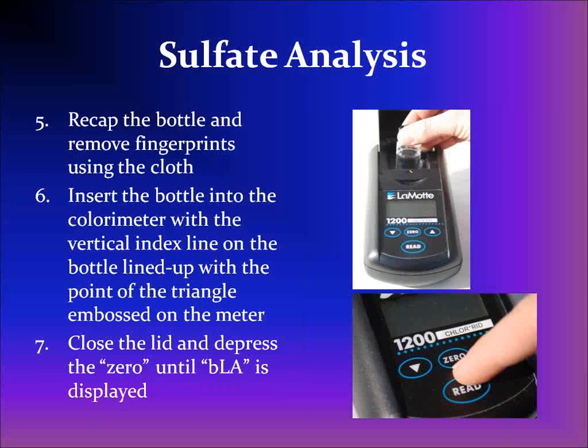After the extract is filtered, replace the cap on the glass vial and remove any fingerprints from the exterior of the vial using the cotton cloth provided with the kit. Any remaining fingerprints can affect the colorimeter measurement.